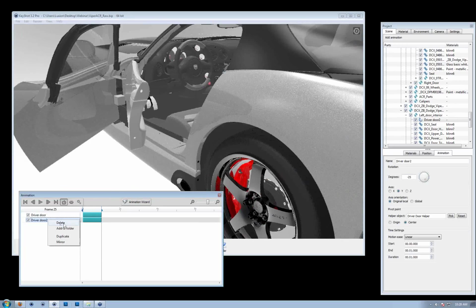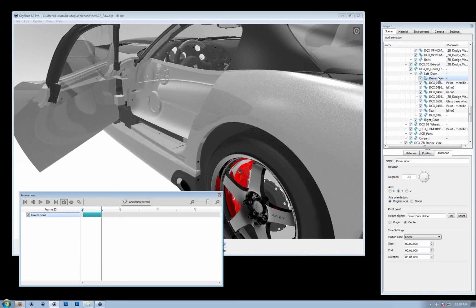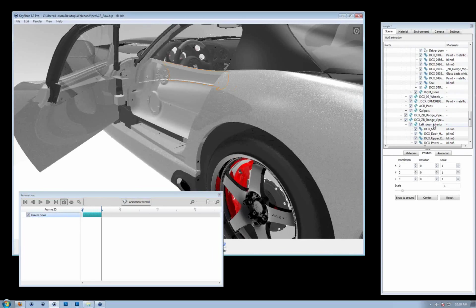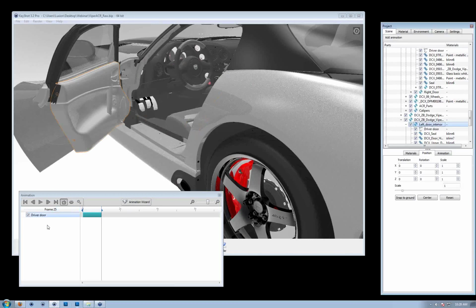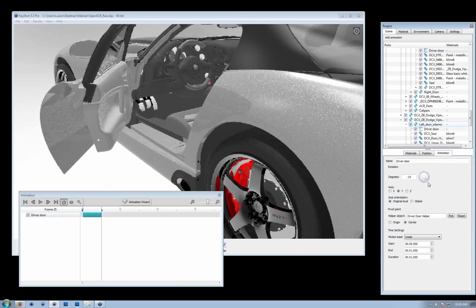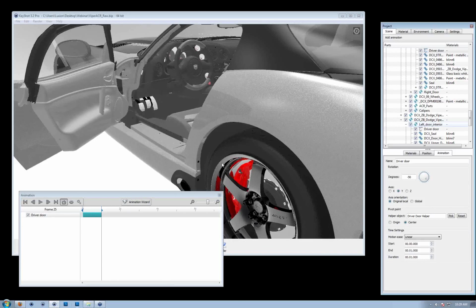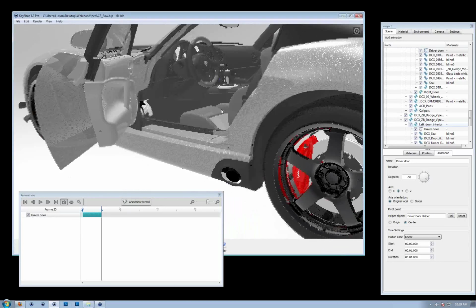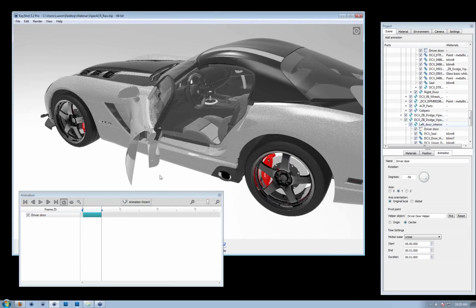So that's one option. Another option is, we'll just do the whole process again. So we, again, copy the original animation, find what you want to animate, right-click, paste linked animation. Now, we still only have 1 animation, so it's a little bit better for organization, and as we modify the degrees here, they move together because they're sourcing from the same animation. So that's a very nice way to do that, to keep that organized. All right, and they're both using that same helper object, so we're all good on that.